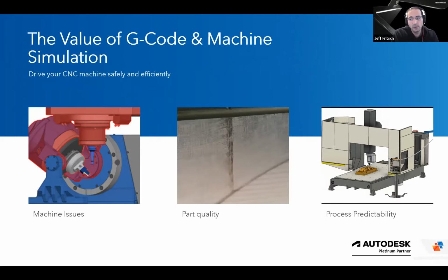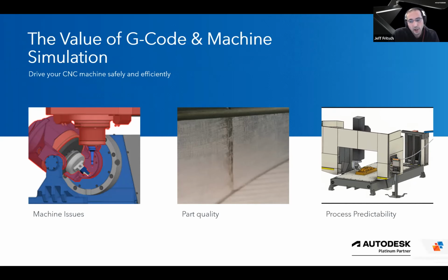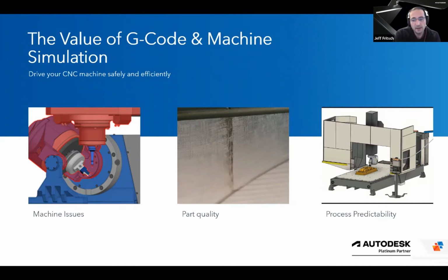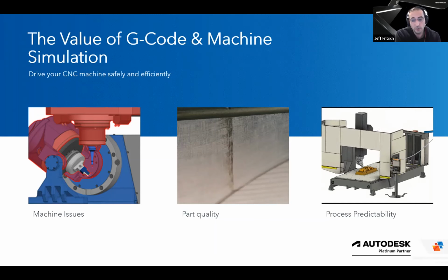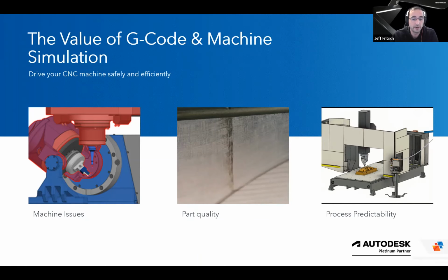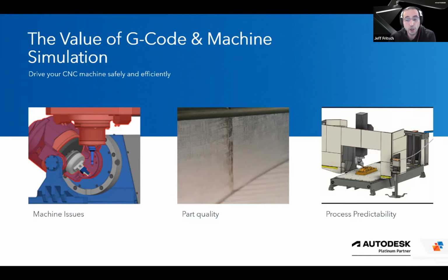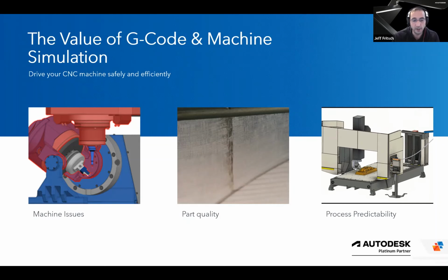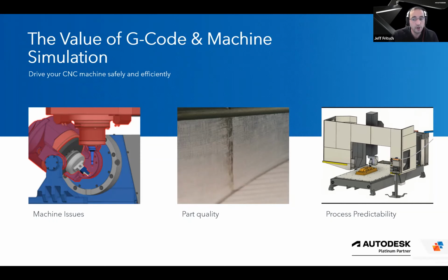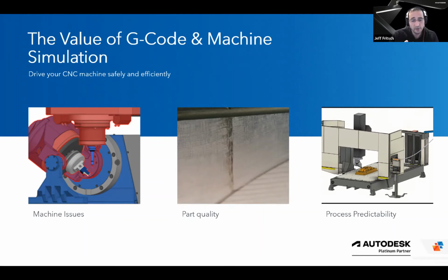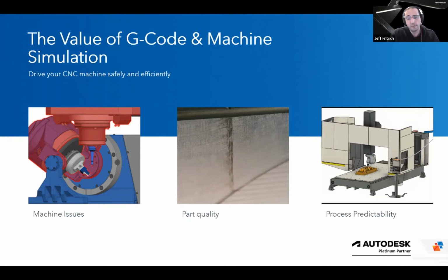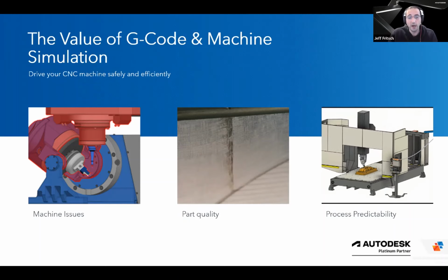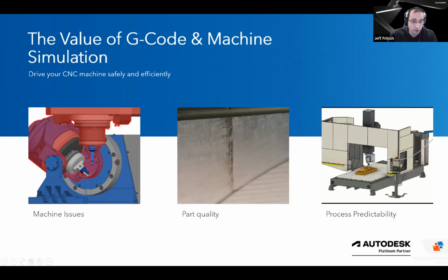So at that point, this is really where CAMplete is going to come into the picture to really help make that connection between the CAM system and the actual code that's going to be produced. And as we're doing this, making sure that the code that has been produced will be able to run appropriately in that machine environment. So would there be any issues, as we've seen in the video, that are not necessarily coming from the toolpath in itself, but really all the elements surrounding the toolpath interfering, whether that's at the code level or at the machine level.